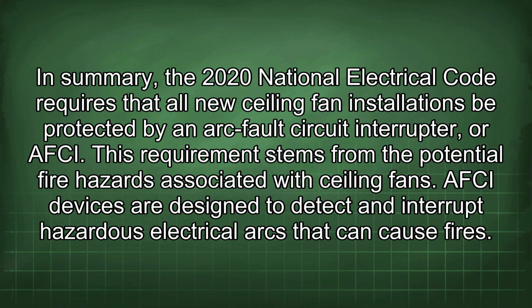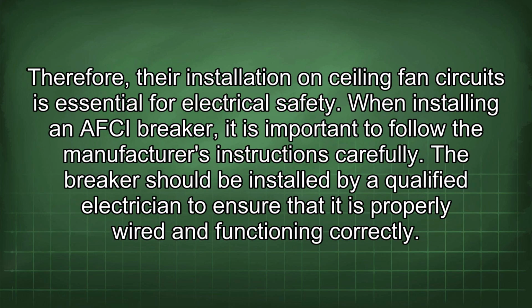In summary, the 2020 National Electrical Code requires that all new ceiling fan installations be protected by an arc fault circuit interrupter, or AFCI. This requirement stems from the potential fire hazards associated with ceiling fans. AFCI devices are designed to detect and interrupt hazardous electrical arcs that can cause fires. Therefore, their installation on ceiling fan circuits is essential for electrical safety.